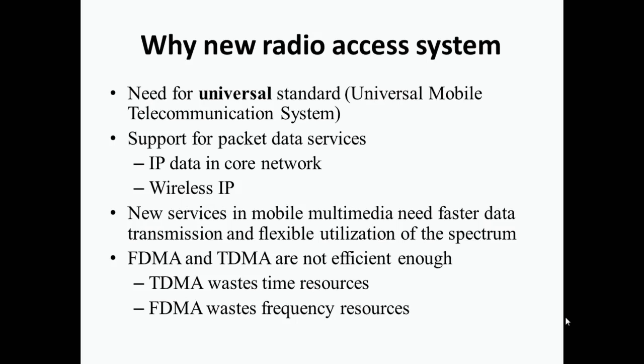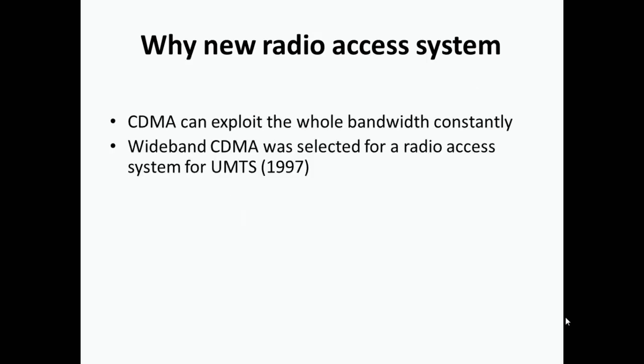Now new services in mobile multimedia need faster data transmission and flexible utilization of the spectrum, as our previous techniques do not provide faster data communication, and spectrum utilization is also an issue. For example, FDMA (frequency division multiple access) and TDMA (time division multiple access) have the following limitations. TDMA wastes time resources, whereas FDMA wastes frequency resources. That's why, to overcome these limitations, we are using CDMA instead of these techniques.